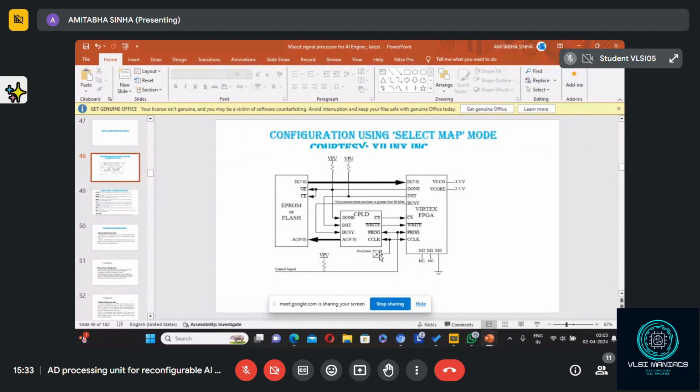Some external clock generator circuit is there, and that clock is given to both of them so that the CPLD and FPGA are synchronized. Otherwise, the CPLD will be giving a write bar signal and the FPGA will be working on its own, and it will not work. There will be a mismatch. So to match, all the signals are with respect to the clock. The clock is the reference. That's why this clock is called the configuration clock.